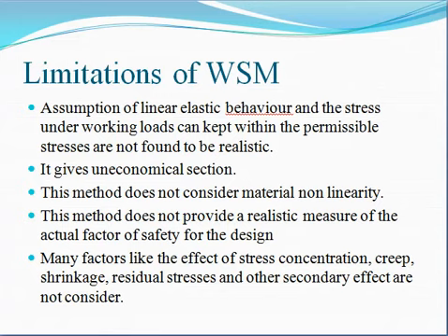Second, it gives an uneconomical section. Uneconomical section means what? The design by using the working stress method is heavy. Means it gives heavy sections, and heavy sections require heavy money. That's why the design which is made by using the working stress method is uneconomical. Third limitation is this method does not consider material non-linearity.